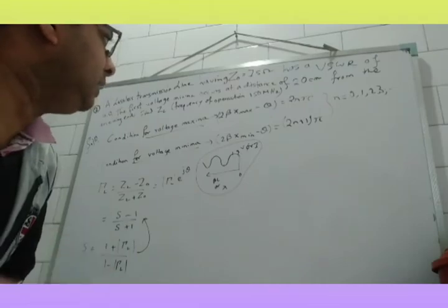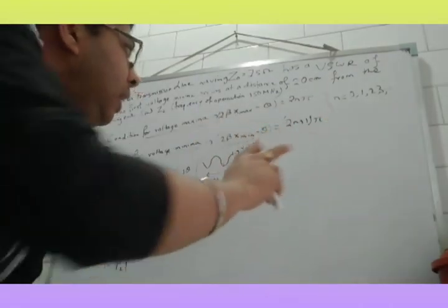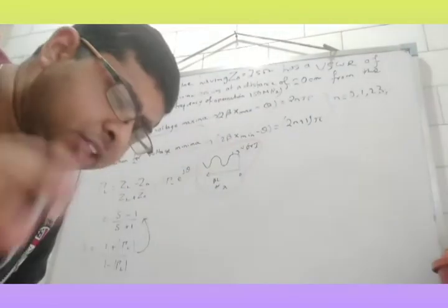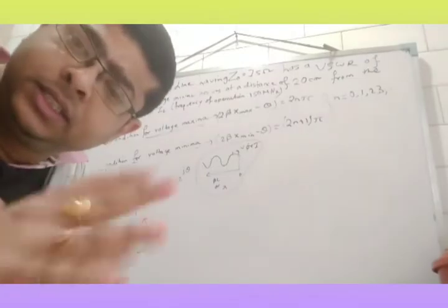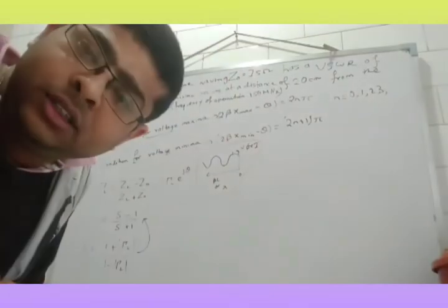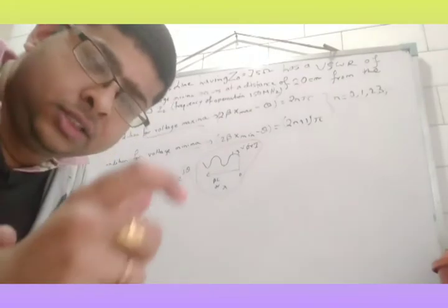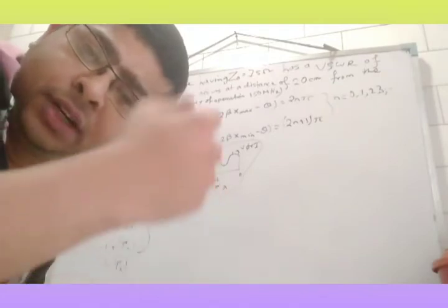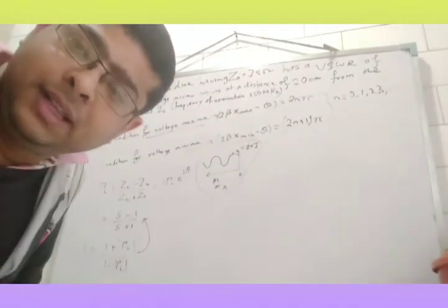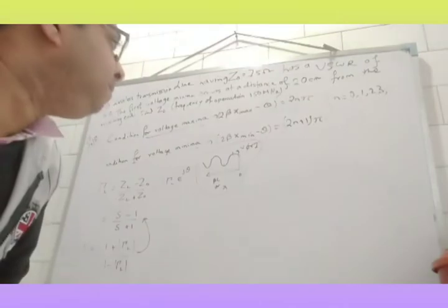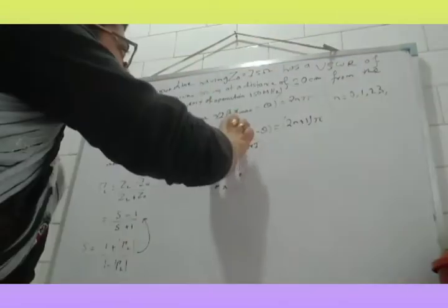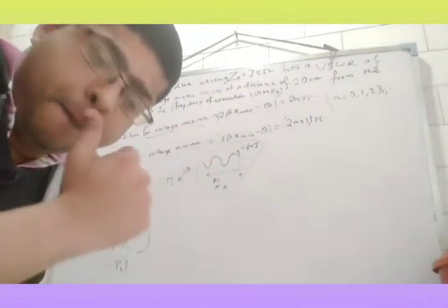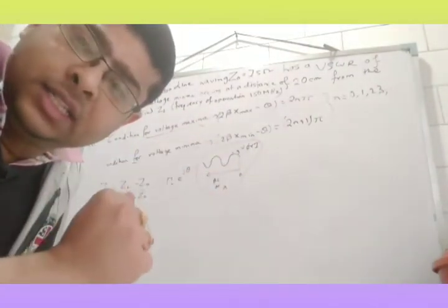And sometimes you will see beta L, as you have seen in the characteristic input impedance expression, tan beta L. What is that beta L? Beta L is the electrical length. Beta is given by the formula 2 pi by lambda, the wavelength, and you multiply beta with the distance L, then you get the electrical length.